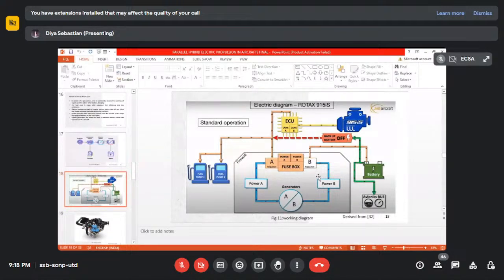The engine operating parameters such as fuel flow rate, stator vane position, bleed valve position, and others are computed from this data and applied as appropriate. FADEC also controls engine starting and restarting. The FADEC's basic purpose is to provide optimal engine efficiency for a given flight condition.